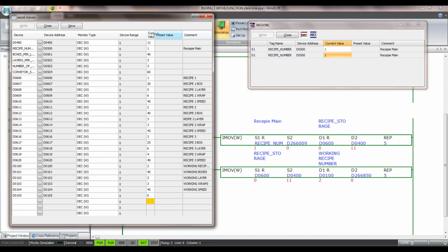If you're using M0, M1, M2, M3, and then you're using Q1, Q2, and then you're using 5 data words, D100 through 105. You can see how using this indirect move and indirect bit move, which we're about to do, you can load those user-defined macros.